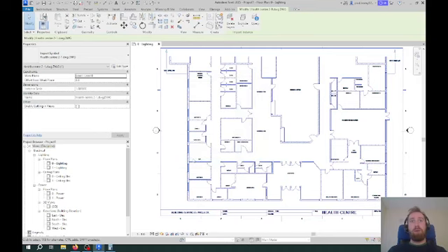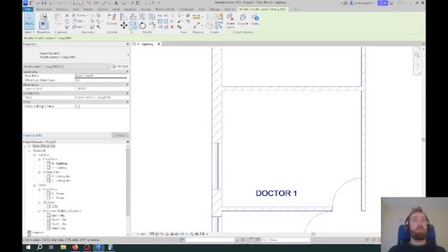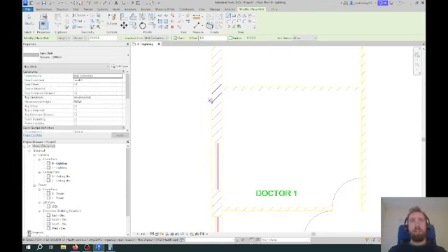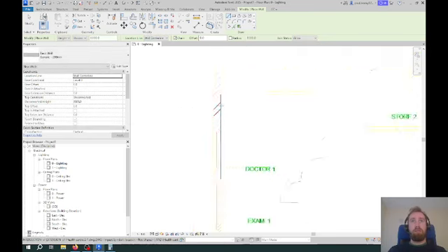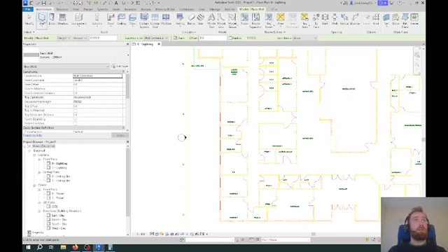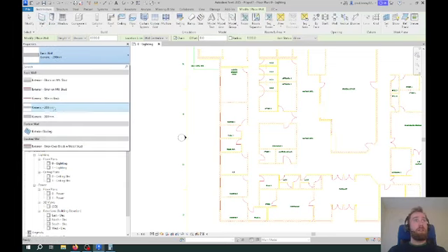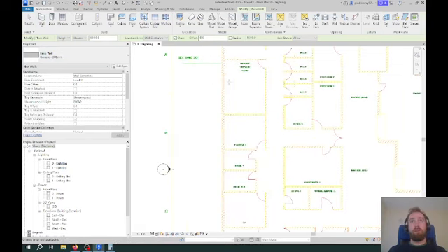But one of the issues is that when we go to start drawing walls and stuff over the drawing, so WA is the shortcut for walls, here our wall is probably just coming in at about 300 millimeters wide. So just as an example, I'm going to go to my walls, pick a 300 millimeter wall for now, just to highlight what I mean by this.